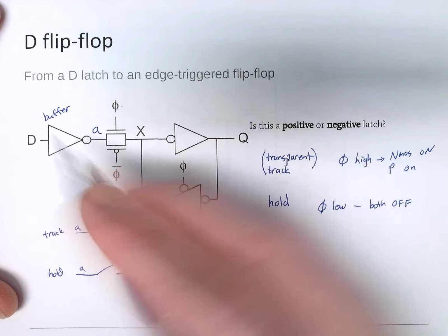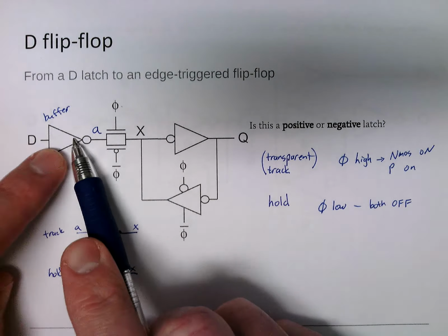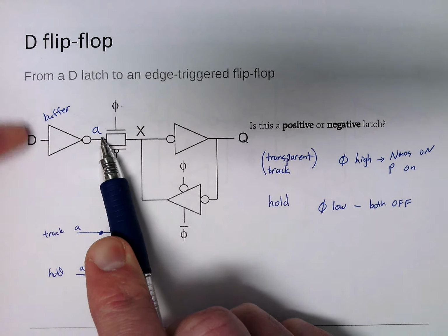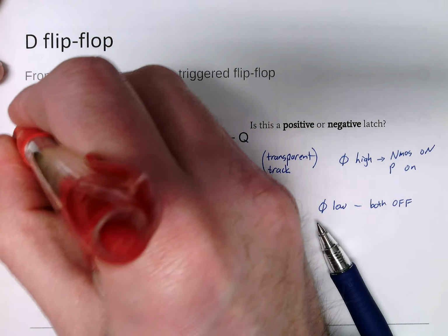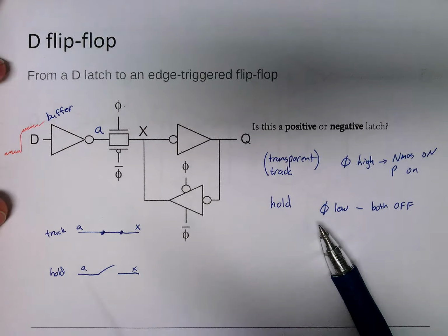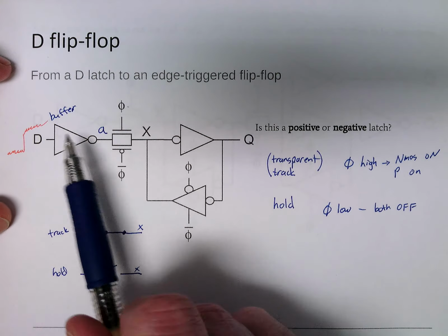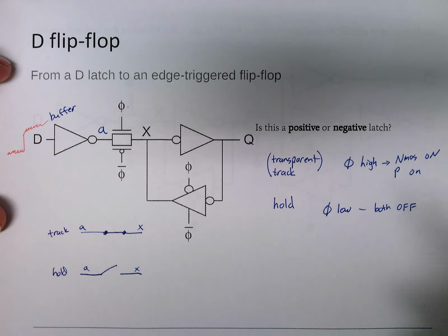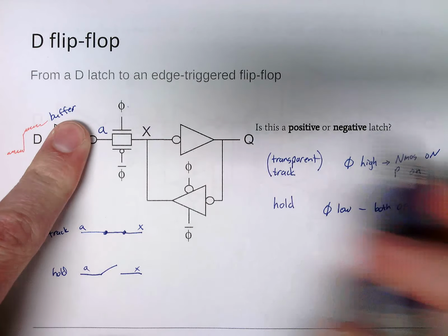It's an inverting buffer, to be a little more precise, but it just isolates node A from whatever noise might be coming in from the inside, or from the outside world. That's always a good idea, but it does take up chip area and adds to our delays, so it's always a trade-off. Another thing, so we can take this out, perhaps.